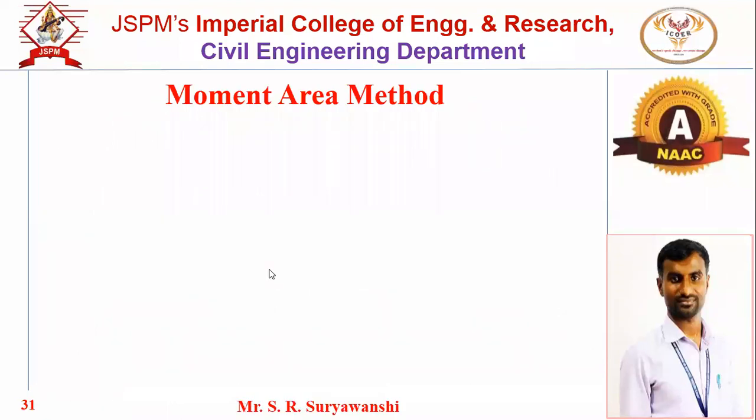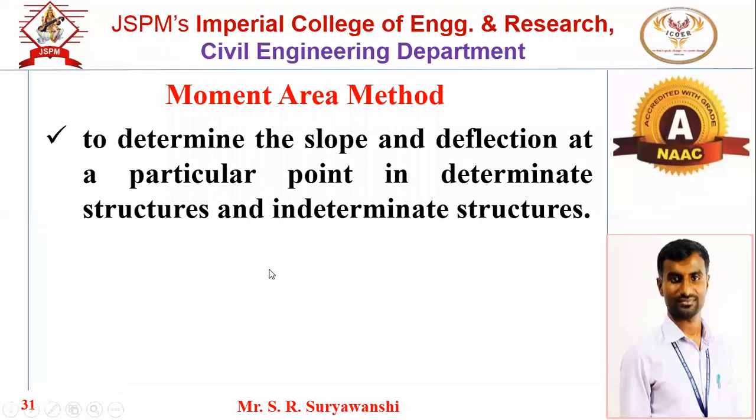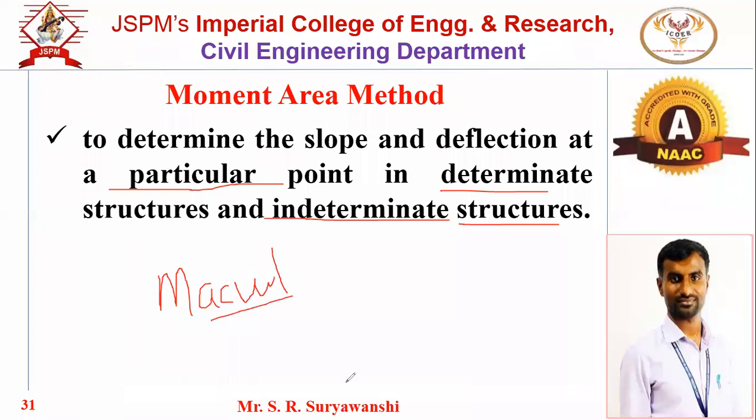This moment area method is used to determine the slope and deflection at a particular point in determinate structure and indeterminate structure. Now in case of Macauley's method, tell me, for which kind of beam you have applied Macauley's method?